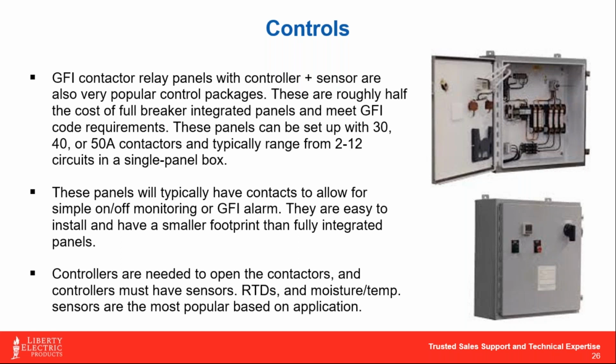So, again, even though the outdoor temperature may have gotten down to 25 degrees a couple of weeks ago or whatever the case may be, it didn't stay down there for very long. So what was in the pipe or the skin of the pipe may not cool down to a point where the heat trace really needed to be kicked on. So, when you look at skin temperature, we like that because it's a lot more accurate and it's more efficient for your system overall, okay?